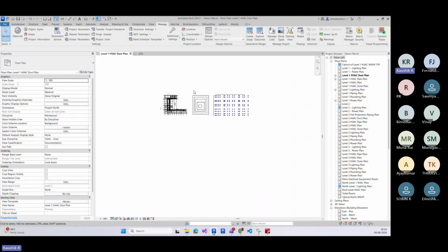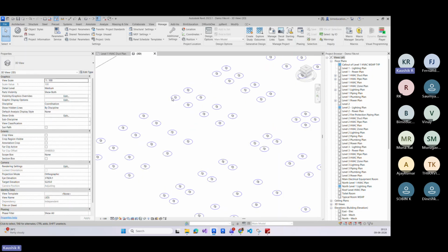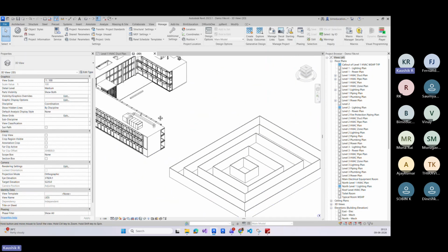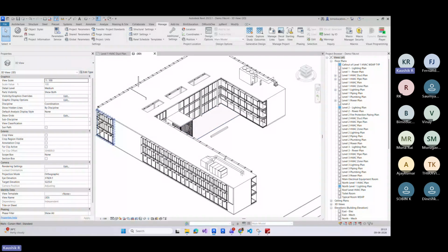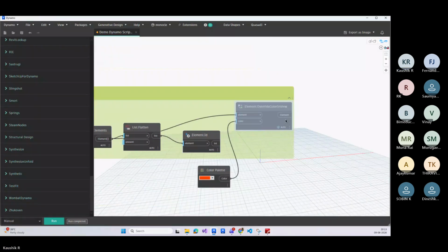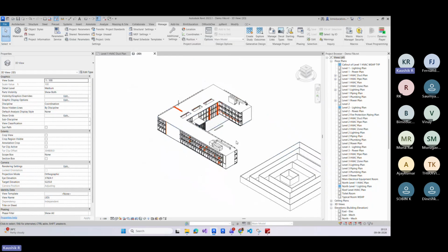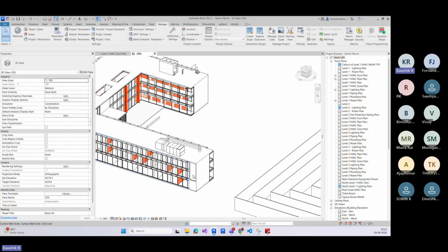So now this is the example for modeling clash. I want to do clash detection between wall and duct. Wherever walls and ducts are intersecting, which means clashing, I want to extract those elements without Navisworks. So consider, minimize, unfreeze. I'm running the tool, run was started and that was completed. If I minimize here, wherever wall and duct were intersecting, those elements are highlighted.